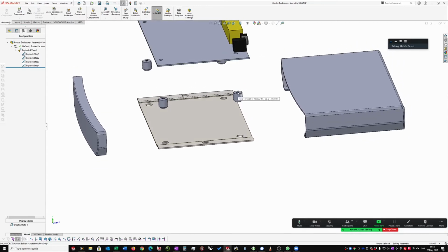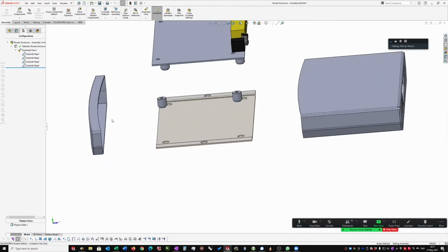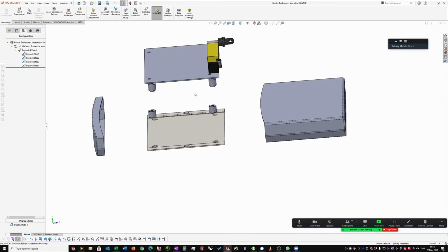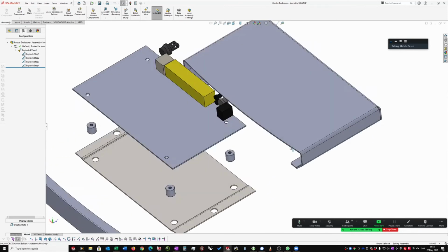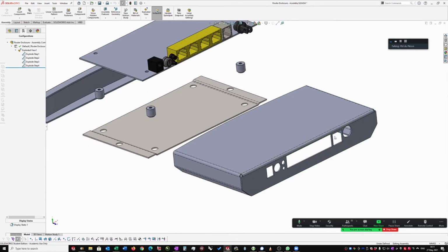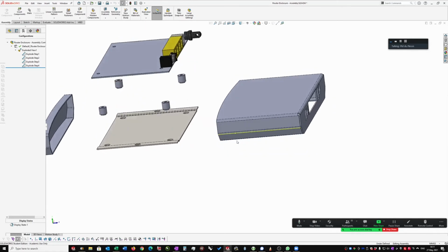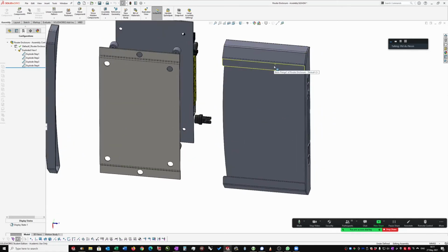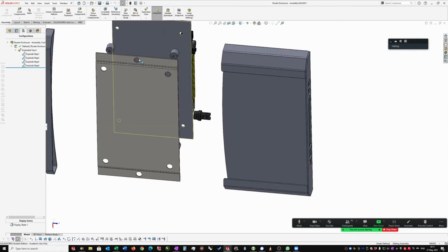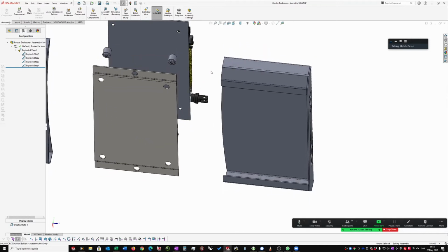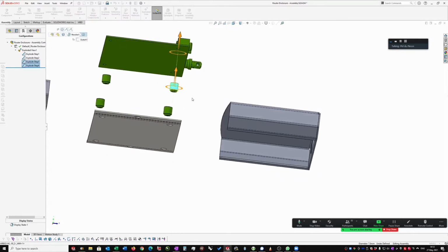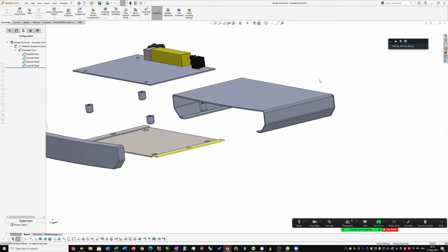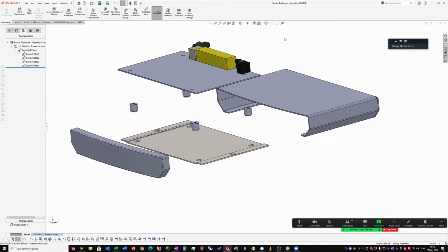So what happens is those get pressed into these holes, interference fit, tolerances coming into play, then that gets screwed onto those standoffs, and then this piece gets screwed onto the base, and that forms a unit. Those three form a unit, which you then slide in because of this jog. You slide in here and they meet those holes in the back, and then one more screw or two more screws will put a screw in there and in there, and there the holes are for the screw inserts, which I'll give you. They'll look like this, but they'll be slightly smaller. So that'll be the project, just so that you have an awareness.